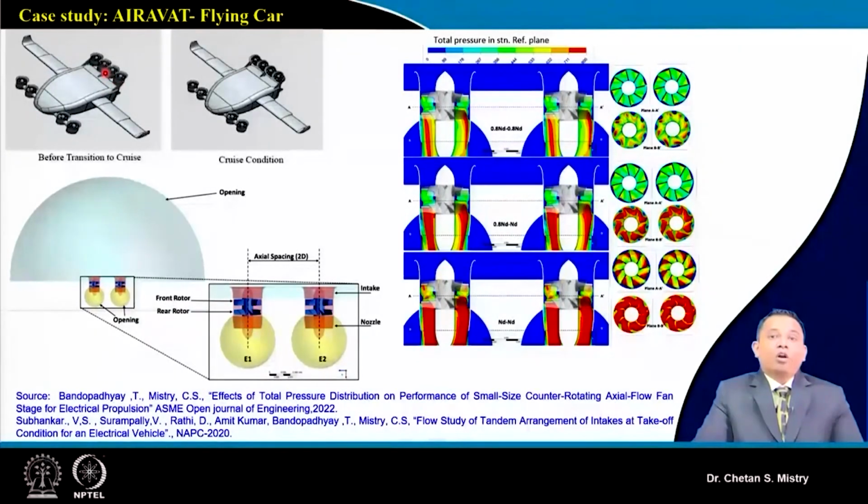Now in order to have light weight, we have discussed these aspects when we were discussing industrial fans. Rather than having one big single fan, it is preferred to go with a number of fans, or a number of motors. That gives benefit in terms of weight, as well as endurance and motor capability, and that is the reason why we have gone with this multi fan configuration.